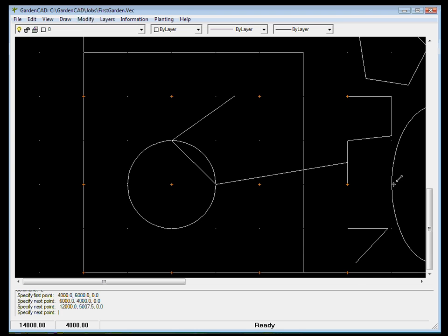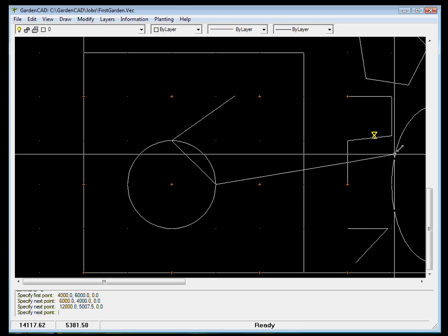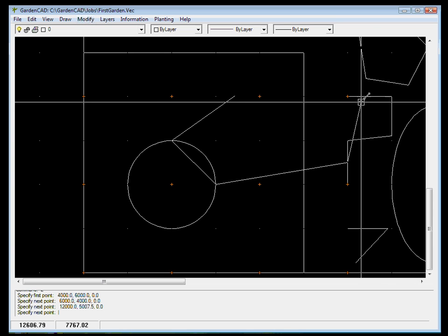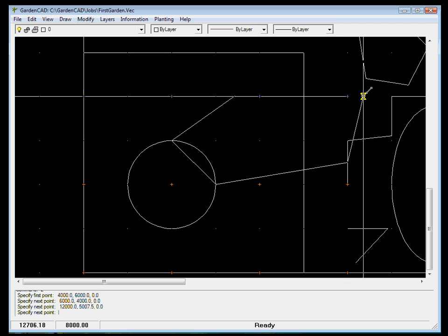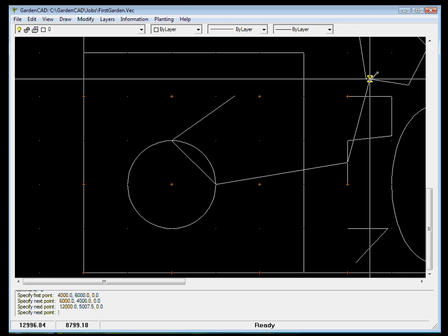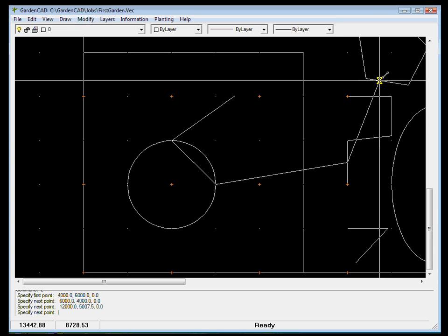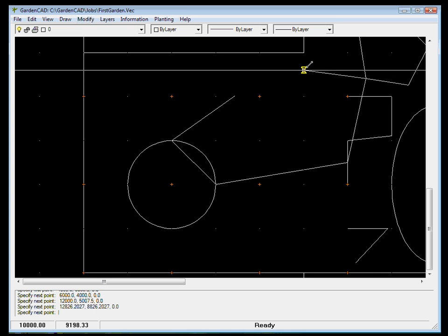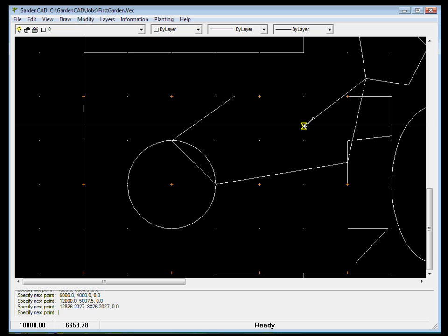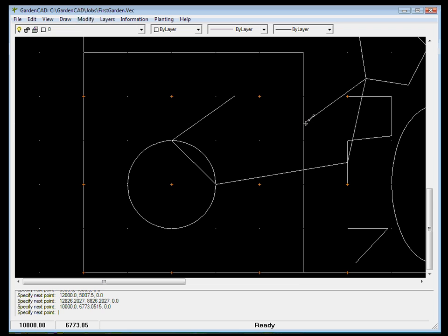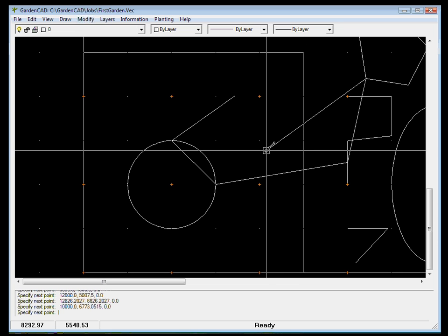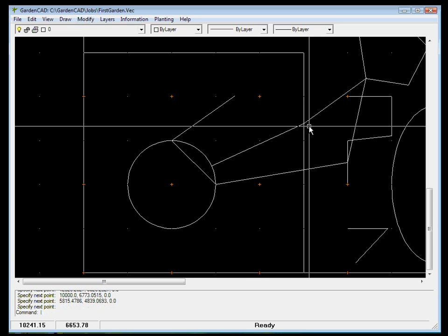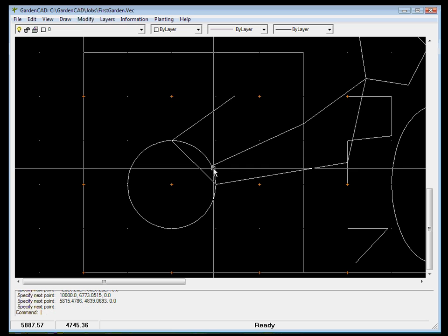Now we could go, I think, perpendicular to... Perpendicular is not coming on at the moment, it's the nearest option there. Let's go across to there, that's still nearest. We may be able to find the perpendicular to this one. No, it's still there. So let's go end point. Surely we can get perpendicular to here. And again, that's not coming. The little crisscross is the nearest option, which just latches onto it. So you can see we have a few little glitches to fix up. There we go, perpendicular to that circle. So that line there comes across there and comes perpendicular.